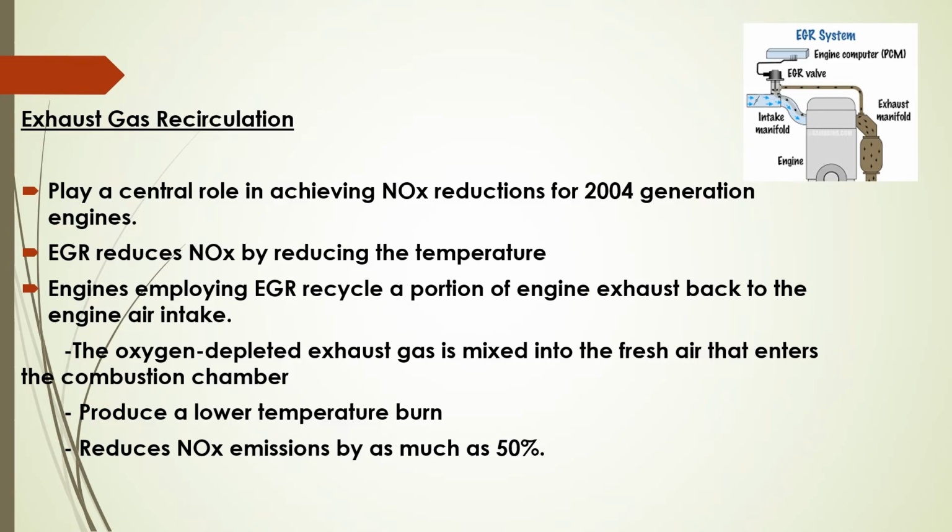Engines employing the EGR recycle a portion of engine exhaust back to the engine air intake. The oxygen depleted exhaust gas is mixed into the fresh air that enters the combustion chamber, which will dilute the oxygen content of the air in the combustion chamber. The reduction in oxygen will produce a lower temperature burn and hence reduce the nitrogen oxide emissions by as much as 50%.